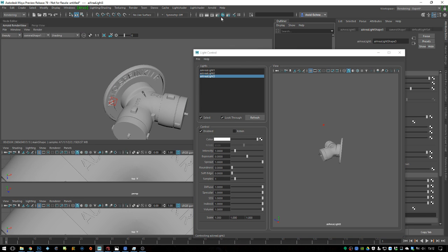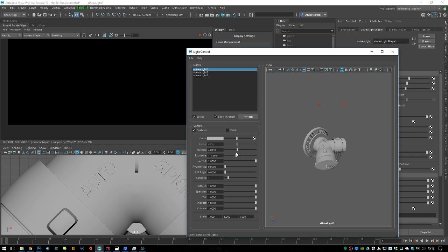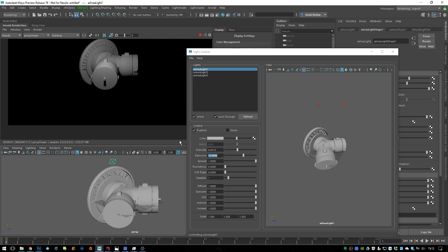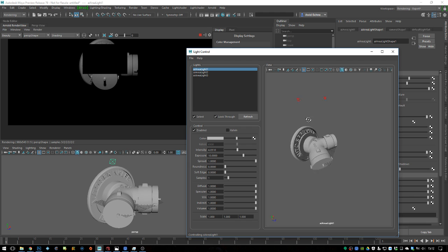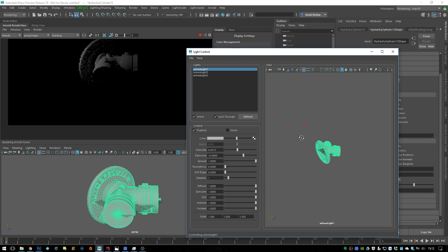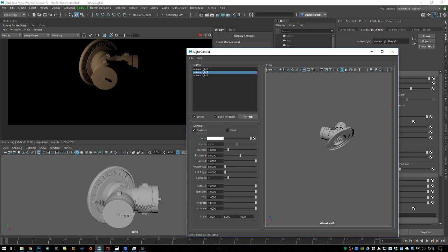So if I start the render now without the backplate, let's bring in some exposure, to 10 maybe. I'll look through perspective. Okay. Now you can have area light 1, rotate this, and let's increase progressive. You can see it's very nice and it's fast. This is now my main key light. I can change the Kelvin color, so orange Kelvin. Then you go to light 2, which is more like a rim top-down light with an exposure of 8 or 10. There you go. Now you can see something going on. You can have a blue Kelvin for this.